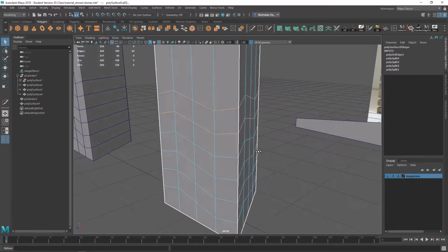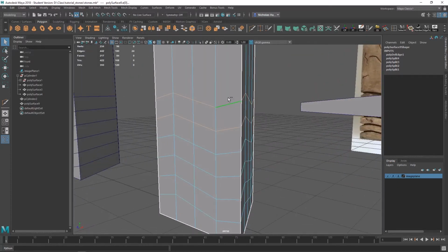And the difference is if you have shift selected, and let's say we've already got these edges selected here, hold down shift, left click to marquee. Say, oh, well, I want to select all these. Shift plus click means add, right? Not really, not in Maya. Shift plus click means select everything other than what you already have selected within the marquee. So you'll notice these two edges, I'm doing the same thing, shift, it's going to deselect those two edges and select everything else. So with shift control click, you'll actually select everything. So shift double click or shift control double click will work fine here.